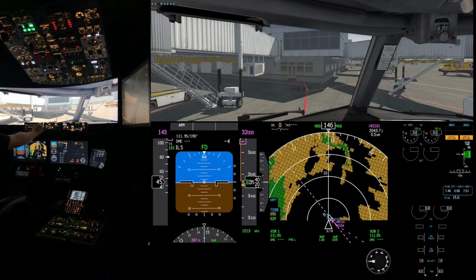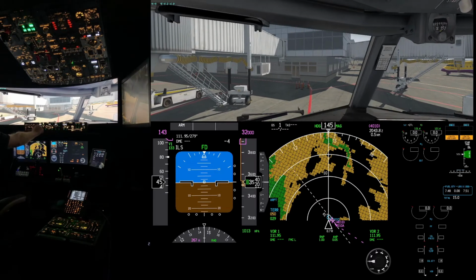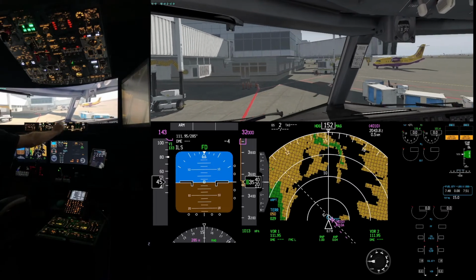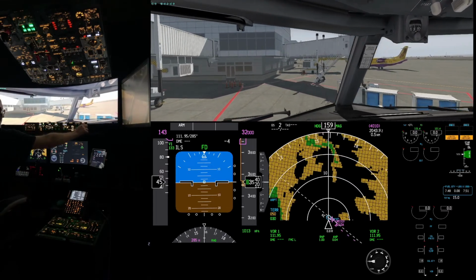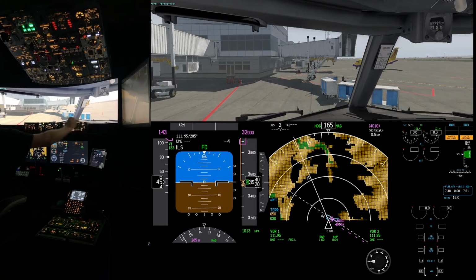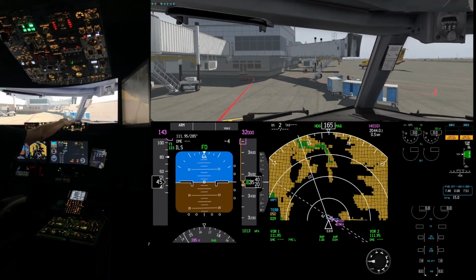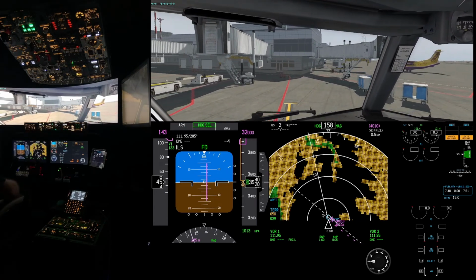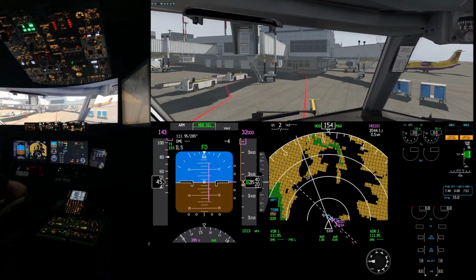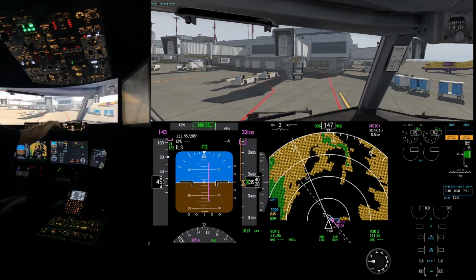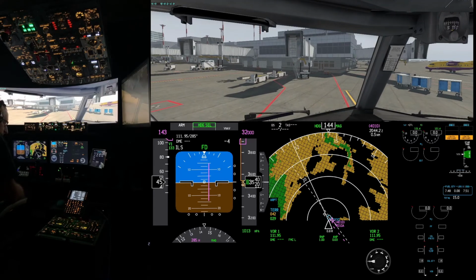What I'm also going to do now is just adjust the course for the airport runway heading for 29, which is 285. I'm also going to pre-arm VNAV and pre-arm heading select for the autopilot. So the course shows the runway heading of 285 and the heading of 285 on the MCP.